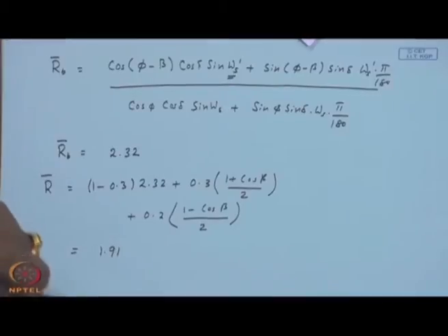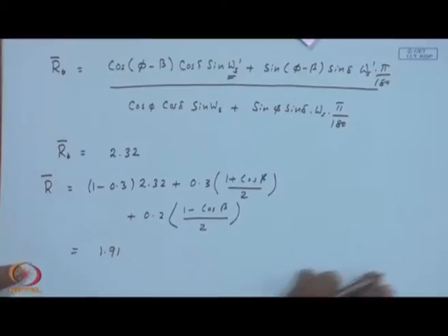Let us just halt for a while. In the course of this problem so far, we used how to calculate the declination, H 0 bar and the clearness index, and then the diffuse fraction and the parameter R bar. So, tilted radiation, diffuse fraction, extraterrestrial radiation and declination, these relations have come so far.